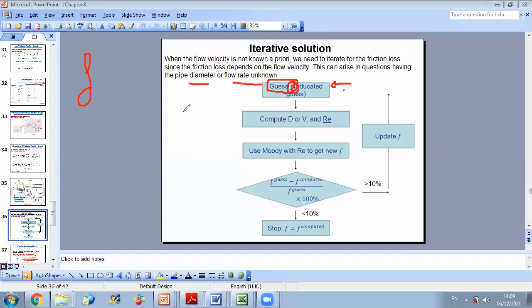Now, which equation am I talking about? As you know, whenever you have a fluid problem, the first equation you write is continuity, the continuity equation for your flow. The mass flow rate is constant. If we have a steady process, we know that m dot in equals m dot out, or the sum of m dot in equals the sum of m dot out. So the first relation you can write is continuity. Continuity will allow you to relate velocities. The second relation you can write is the energy equation.